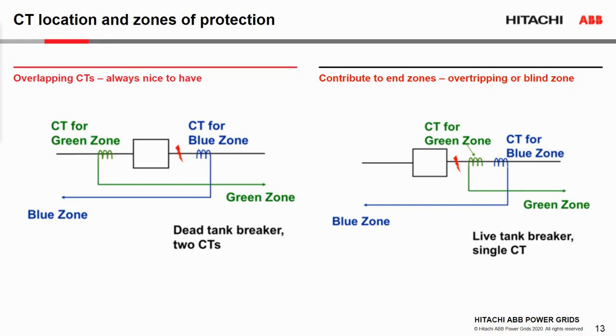There is a solution for this, and it depends on the performance requirement of the protection, essentially the speed. You could wait until the breaker failure protection operates, typically in 9 cycles or 12 cycles, to take this fault apart by tripping adjacent breakers.